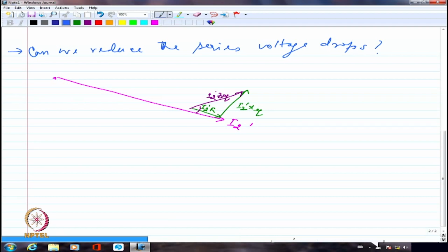When you choose a wire for a particular gauge thickness, you are going to assume that the entire cross-sectional area is occupied by the current. So if the outer shell is not occupied by the current because it is highly resistive, then you are overheating the inner core, which is not good, right?